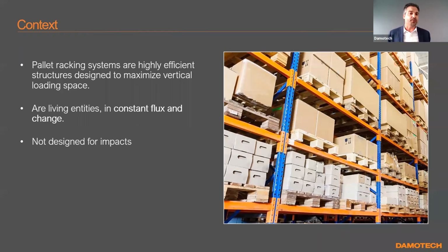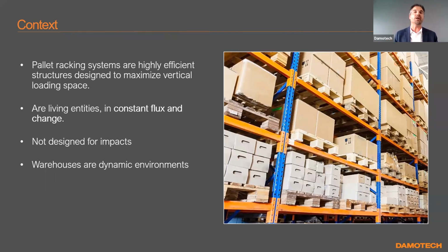Here's the harsh reality about racking. As I mentioned, a racking system is an efficient structural design. They're not designed for impact. So we always make the mention, forklift versus rack, who's going to win? 100% of the time, the forklift will win. So it's important that we think about the risks associated with racking from those impacts.